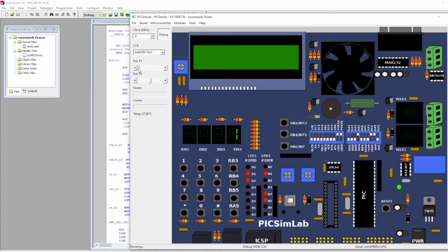And now I'm playing with the potentiometer to enter the second state. Okay, so then it reached 0.4 volt. That's why it displays true. So later, if it reaches above 0.6 volt, it will go to third state. Yeah, and the fan is on. LED 1 lights up, LED 3 lights up, LED 2 is gone, because we already set them off, indicating we are in third state.